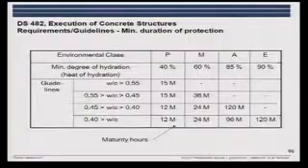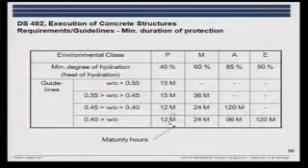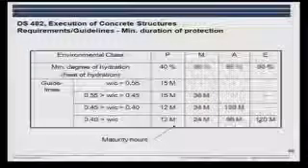Or if you have higher temperatures, you can proceed after fewer real hours. Then you will see that you have increasing requirements to increasing degree of hydration, and that's reflected in guidelines giving increasing amount of maturity hours. So 120 hours at 20 degrees, or double up at 10 degrees, or half at 35 degrees.